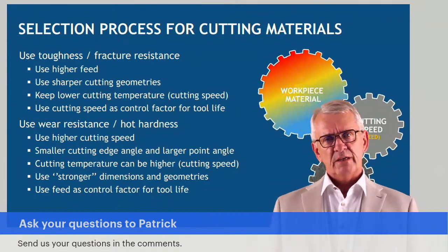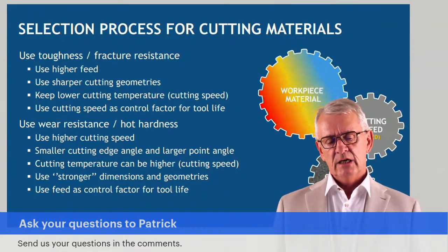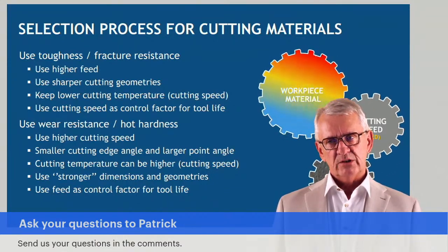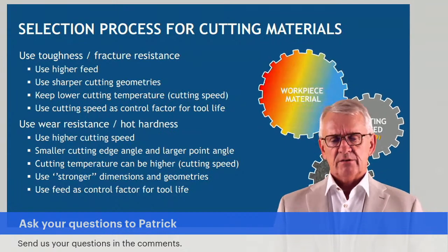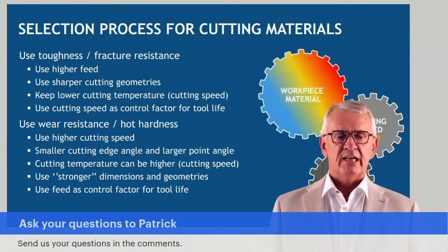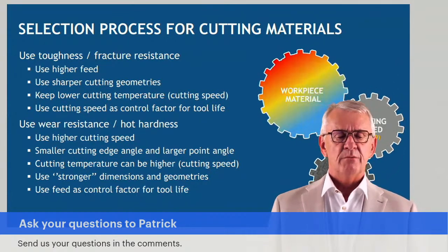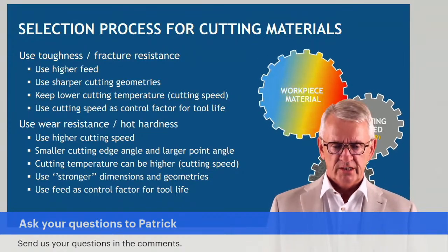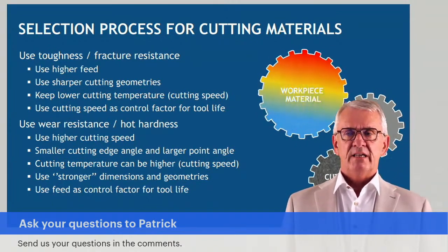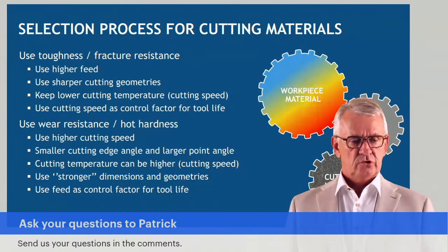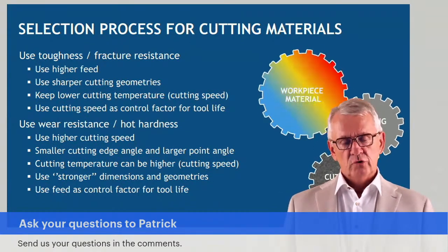And in the toolbox of every machinist should be this awareness: whatever cutting material you select, you should know the main properties or the big advantages. Is this cutting material mainly wear resistant, or is it fracture resistant, or whatever? And then you should exploit that in relation to the workpiece material and the demands the workpiece material will put on the cutting edge, and exploiting the advantage of a cutting material you do by an intelligent selection of cutting conditions.